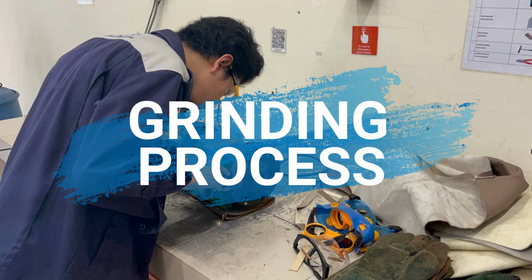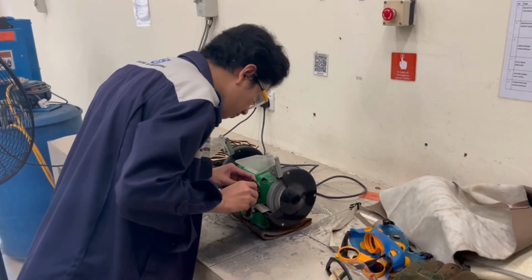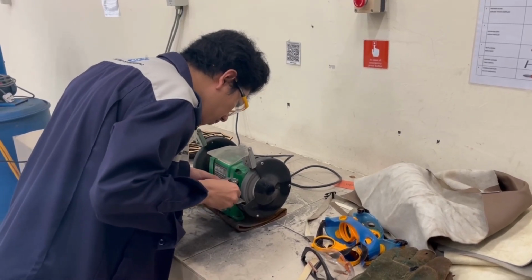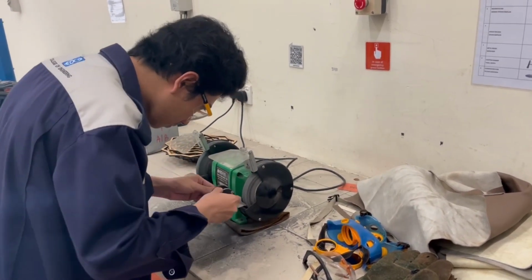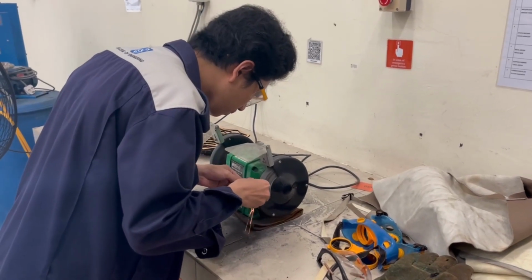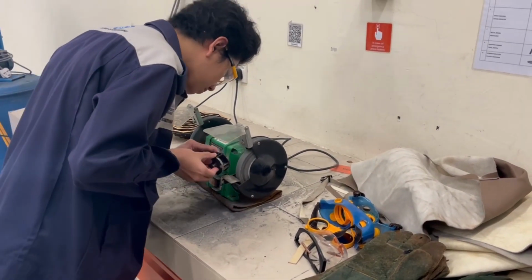For finishing, we grind our workpiece by using a grinder. This is to remove rust on the workpiece and remove overweld on the surface of the workpiece. We turn on the grinder and roll the grind abrasive a little bit to start the rotation of the grinder. We then proceed to grind the workpiece carefully to avoid injury and to avoid over grinding our workpiece.